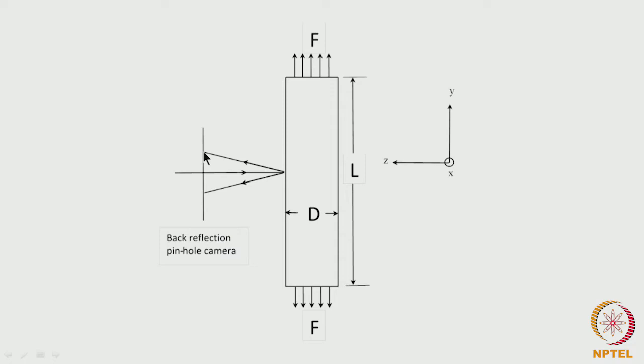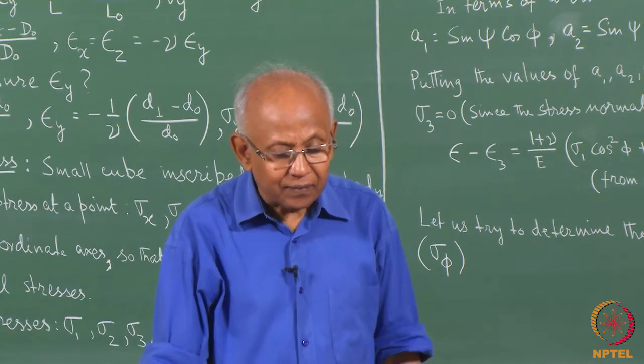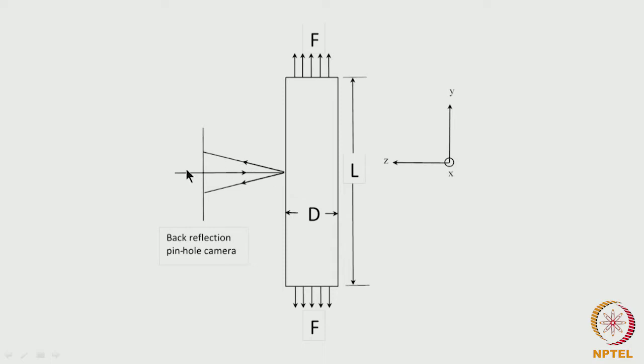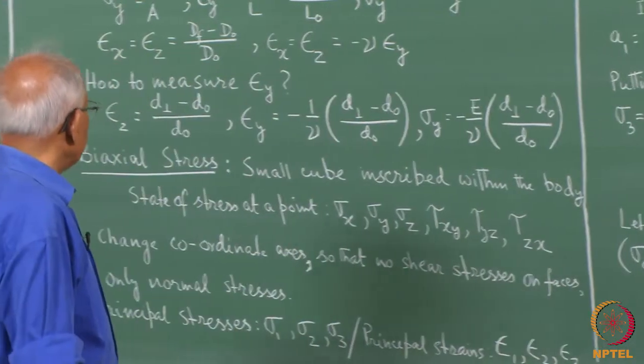So, in fact, we can measure the strain in this direction, and from that we can find out the strain in this direction and finally calculate the stress in this direction. So, this is exactly what we do.